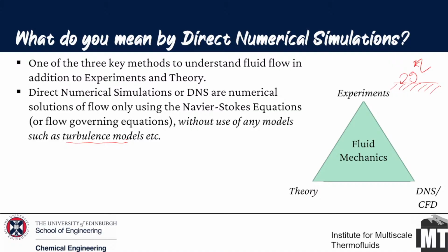have a turbulence model, if you use the RANS equations, there is a term ui dash uj dash whole bar. So this is the main term, which is the Reynolds stress term, and there is a rho or a mu rho in front of it. So this is the Reynolds stress term, and this is always a question mark. So turbulence models always have some sort of an approximation to solve this model.